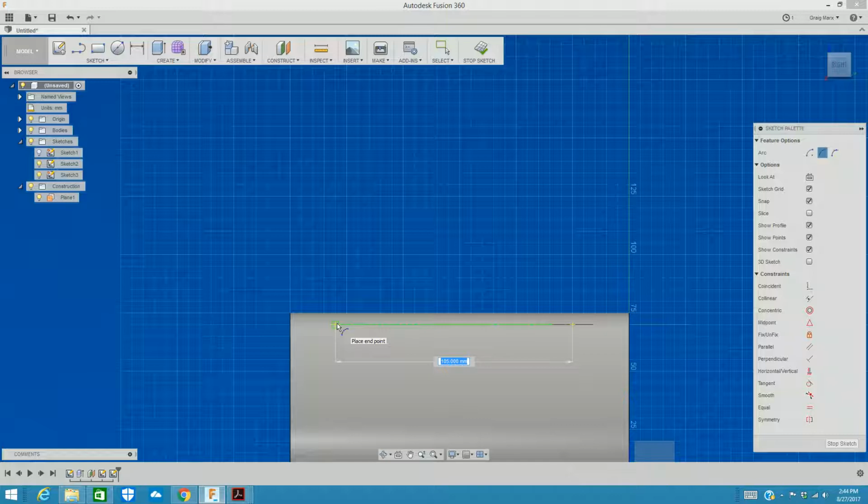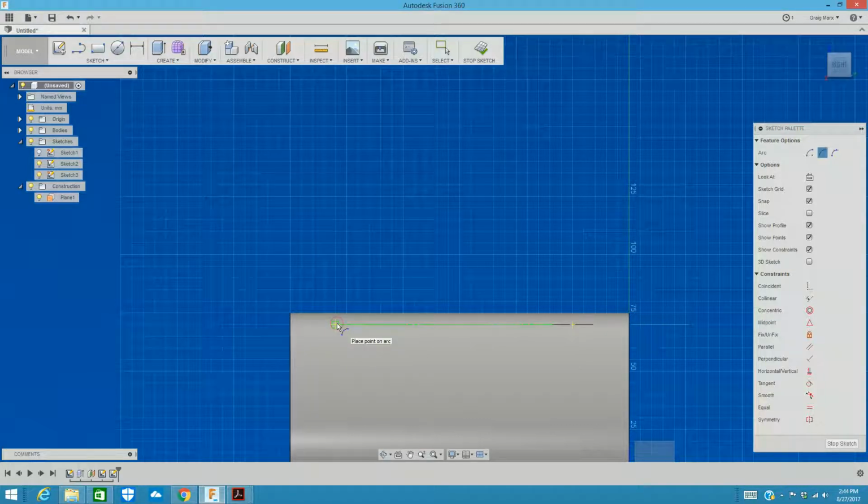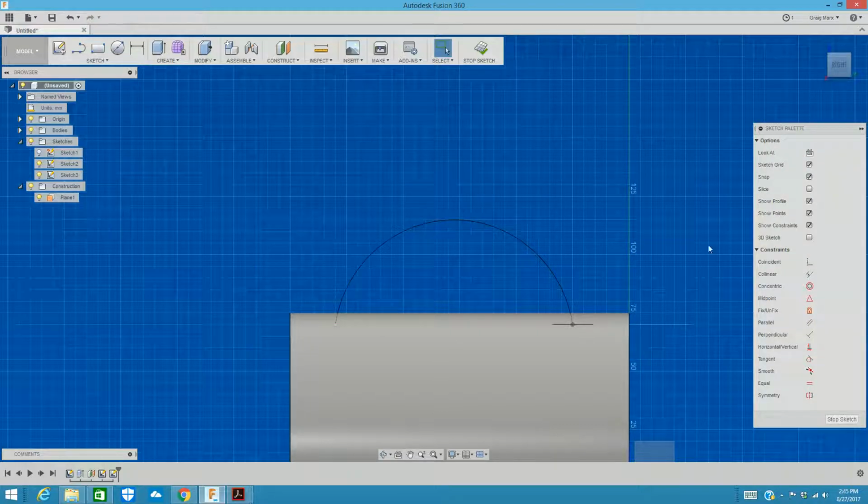I'm going to go ahead and make that 105 millimeters for now. If I wanted to change that distance, I could, but when I click for the second time, now I have this arc preview. And I can make that coffee mug arc go wherever I want. I can make a crazy mug like this, or I can make a pretty normal mug. I click a third time, and that line pops up, and there is my arc, which looks like a semicircle.